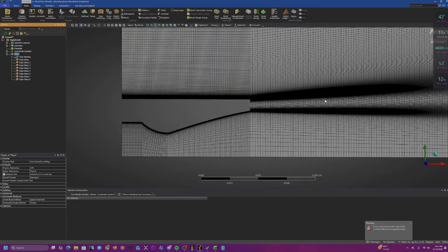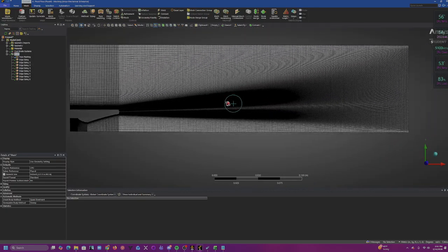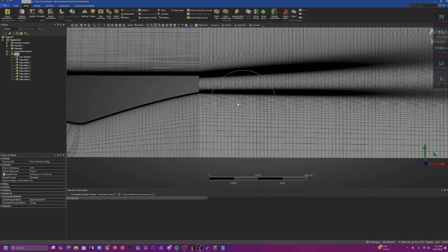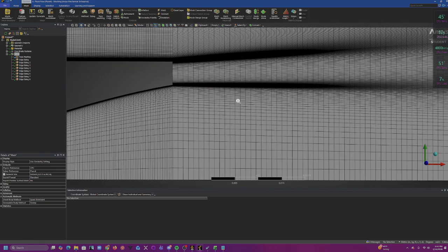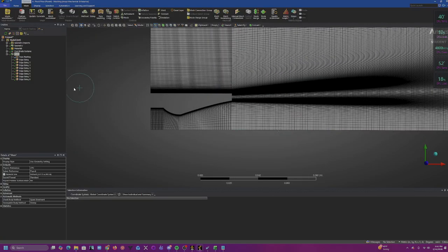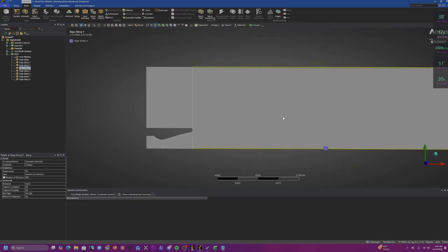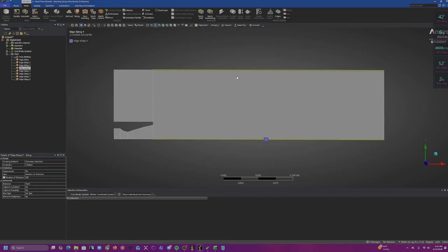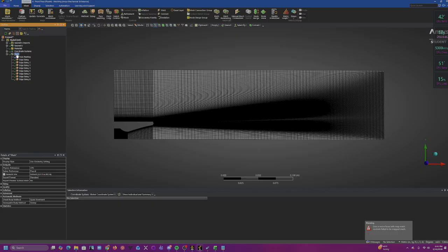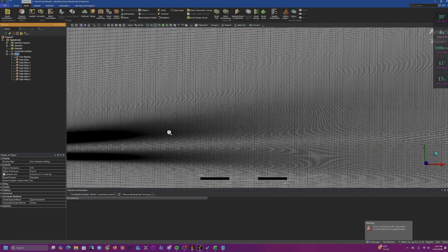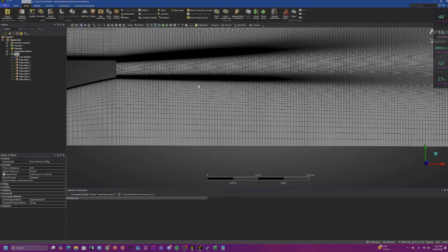Fire, okay. So you should have something like this. Honestly, what we can fix is we can add some more divisions in edge sizing 4, if you guys followed along. Edge sizing 4. So we could add some more divisions. So maybe put 400. Let's see what 400 does to us. See if it does us good. Let's see what happens. 400. That's pretty good. It's not bad.